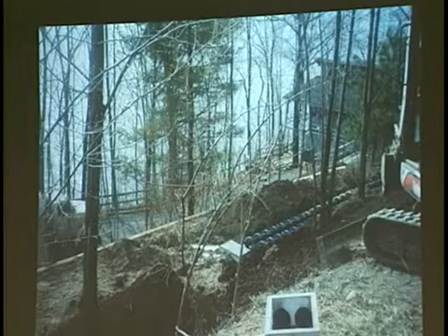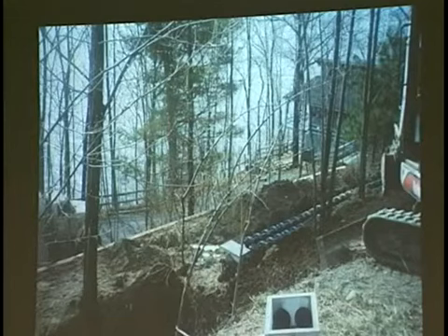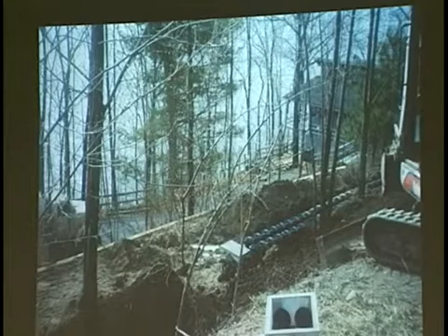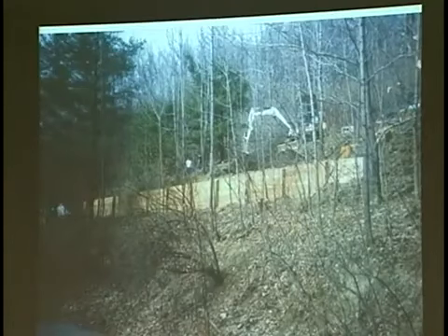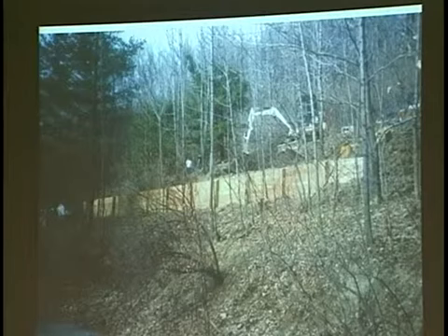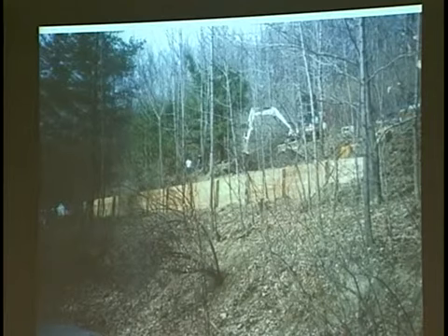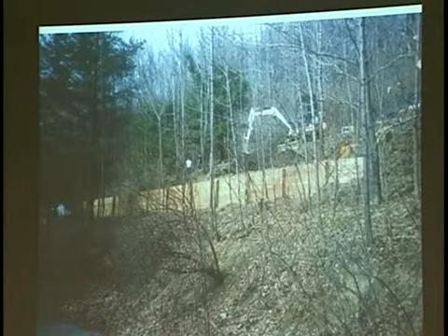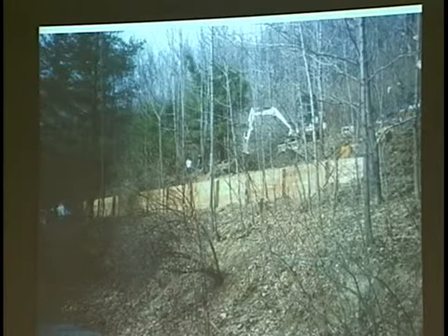So we converted it and got rid of the old steel tank. We put a solids handling tank down in here, pumped up to an aerobic treatment unit, and put the leach system in here. And in order to put it in here, in this part of the embankment back 100 feet from the lake, we had to put a cribbing apparatus in there to hold the soil. Now, why did we put it up here? Because I've got this vegetation, trees, shrubs, whatever, downhill from it. We're going to get some nutrient removal. Am I going to get 100%? No. I'm practical enough to know I'm not going to get 100%, but we're going to get some nutrient removal.